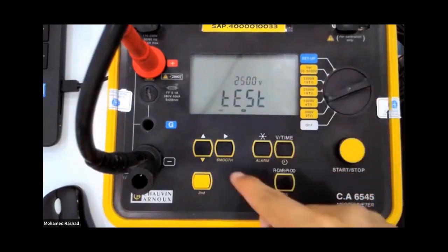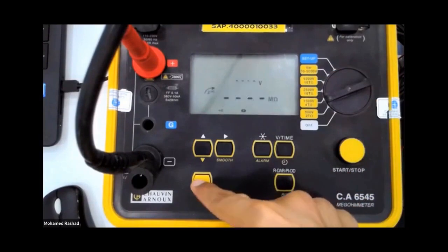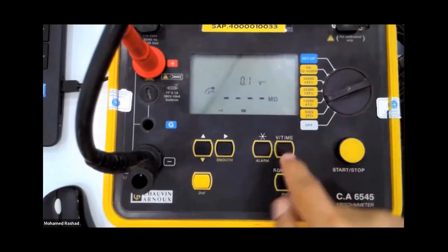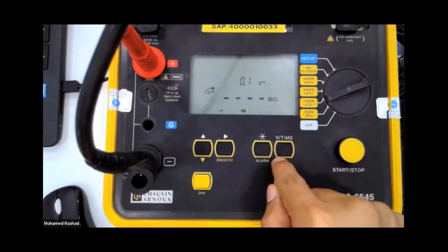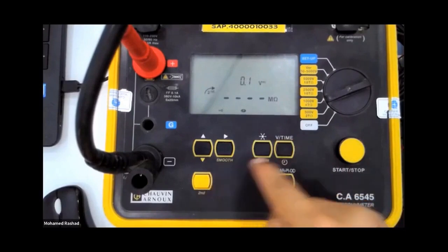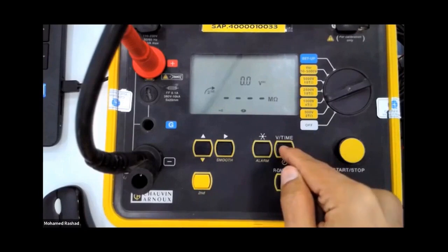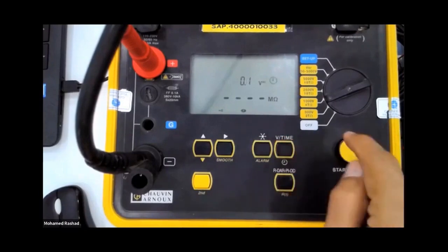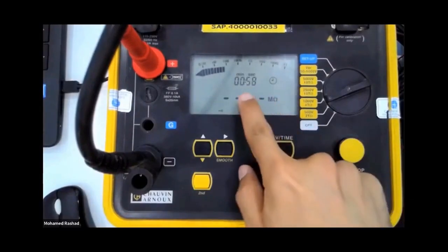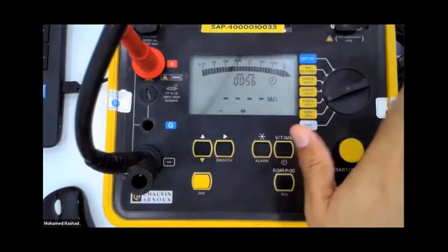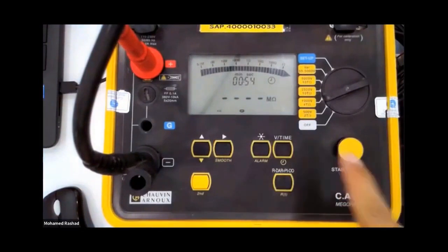Before I do the test, I also press this yellow button, then this button. Why? Because above this button it is written in white that it is voltage or time, but it shows you the time in the form of a clock in yellow. If you press this along with that, it's like you're telling it to activate the time function. So I pressed it and pressed OK. It will show me the time in front of me counting down. As soon as it reaches 0, it will stop the injection all at once.